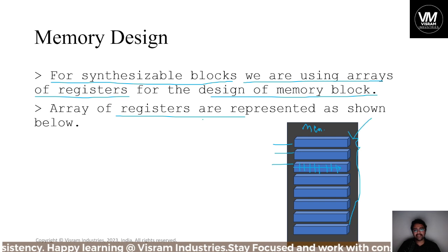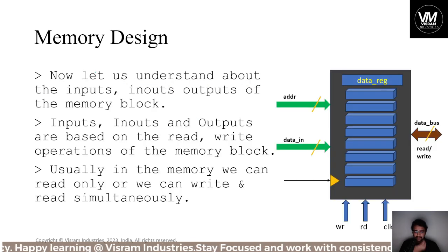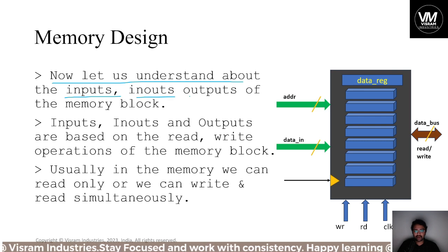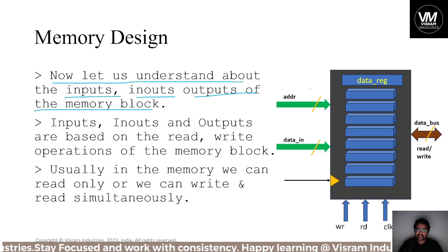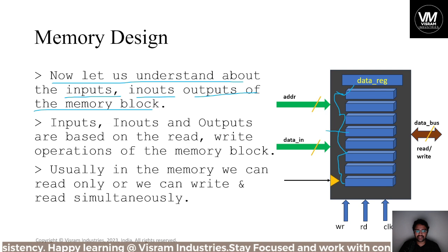Coming to the memory design, what are all the inputs and outputs that we should know? Let us understand the inputs and outputs of the memory block. As we discussed in yesterday's class, an address location should be there for each register, from which location you should be reading, or for which location you should be writing the data.